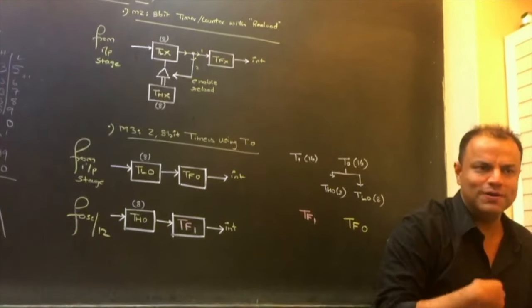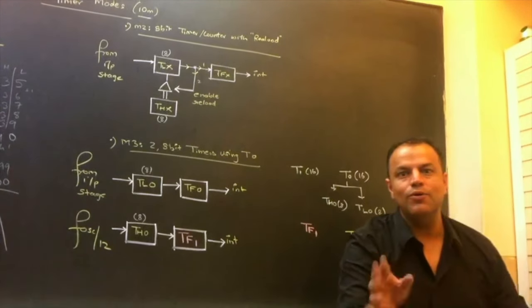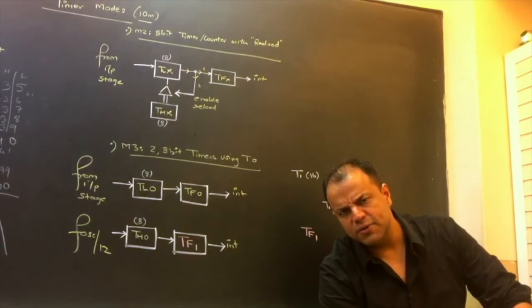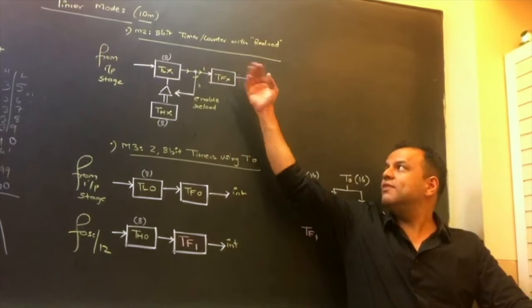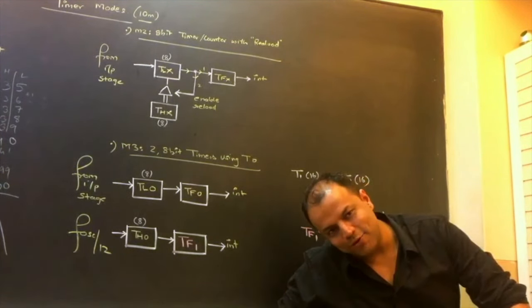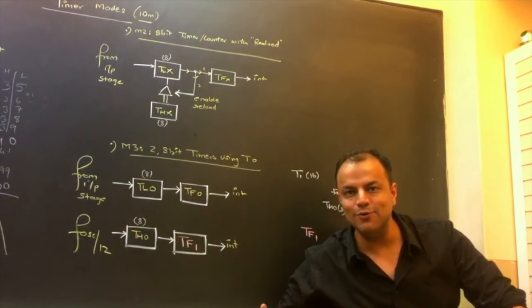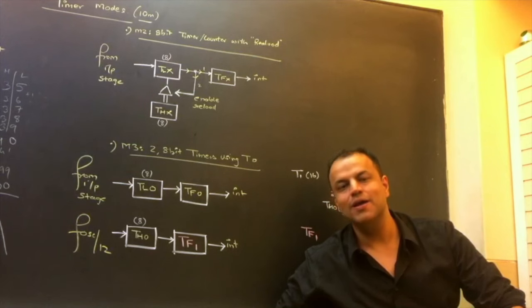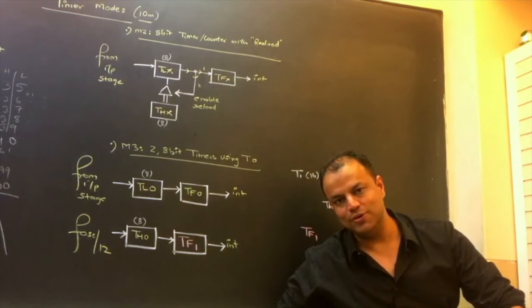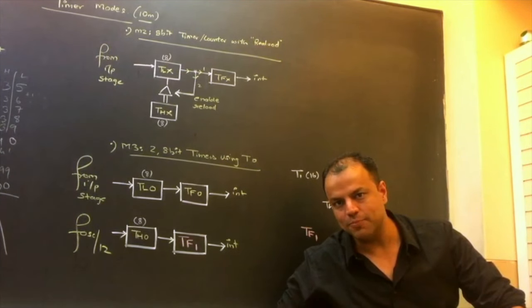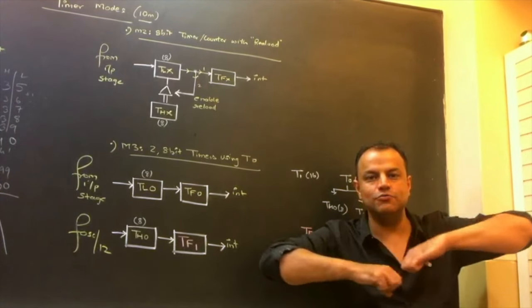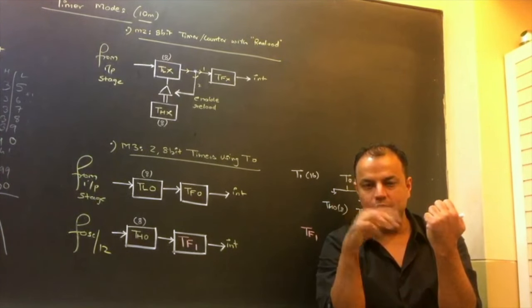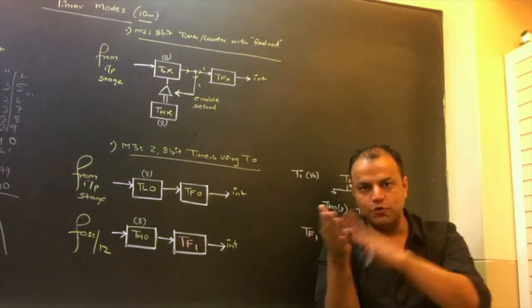We can also reload, but I don't want to reload it myself. I want it to automatically reload. Did you understand? Now, you may wonder why is it an 8-bit mode? That is very obvious. What is going to be reloaded? The count. Random count or original count? The original count. Are we going to give the count? No. The system has to store a backup copy of the count. That means the system has to make 2 copies of the count. One will be used for counting, one will be used for reloading.